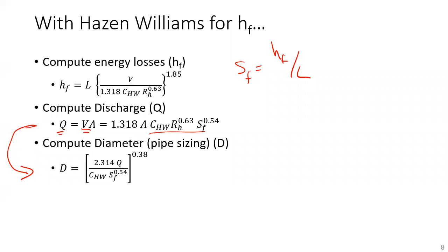And so again, when we use the Hazen-Williams equation, it's a simpler solution path than it was when we used Darcy-Weisbach. That's again why the old timers like it. So one big note. With the Darcy-Weisbach equation, we can either have it as we've always seen it, or when we identify that velocity is discharge over area, we can substitute for v squared, Q squared over A squared.